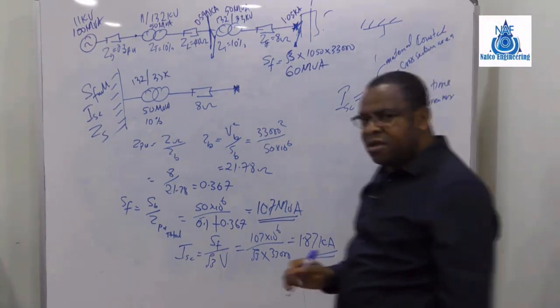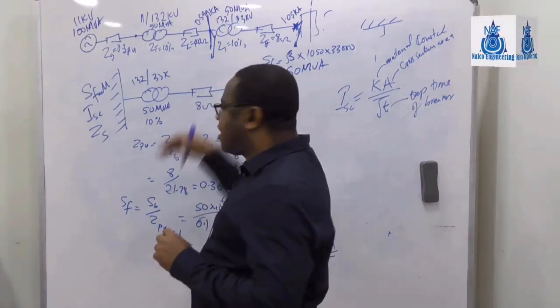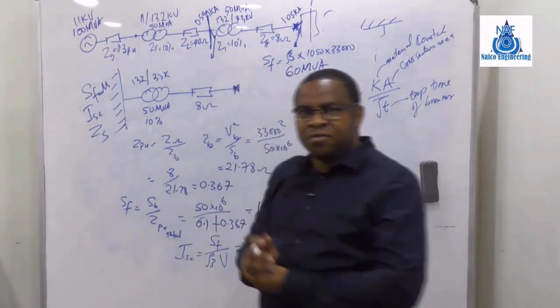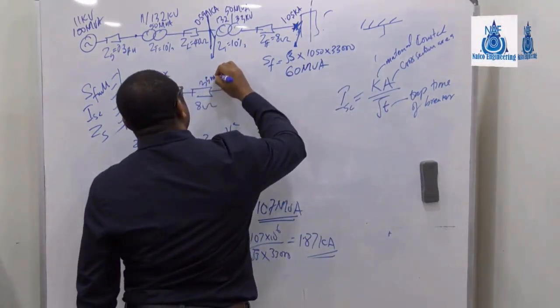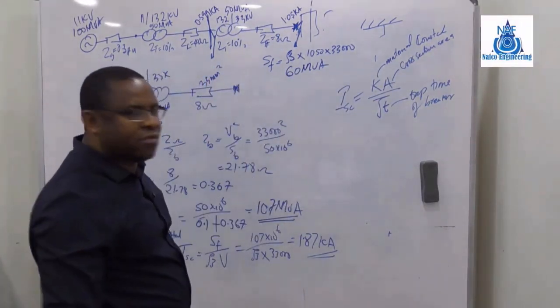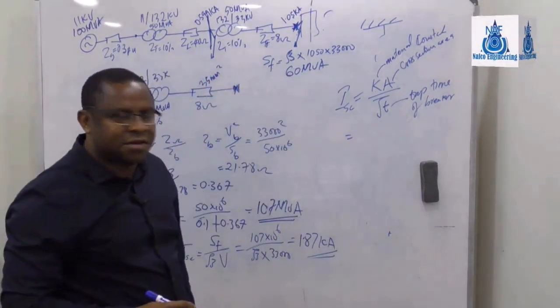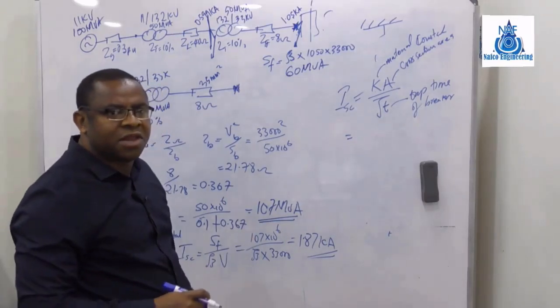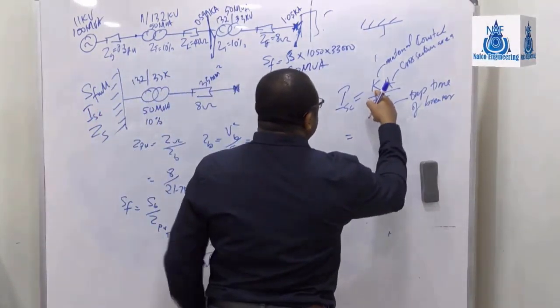The time it will take the breaker that is protecting that cable to trip. For instance, let's assume that this cable is a 35 mm² cable, right? So the amount of current that this cable can handle without damage, let's say in 1 second, will be the K of that.